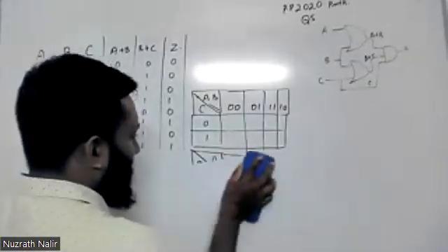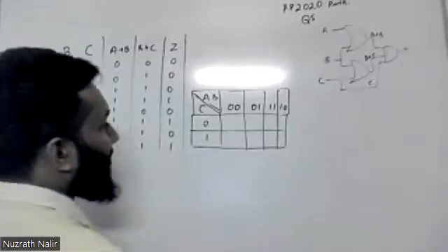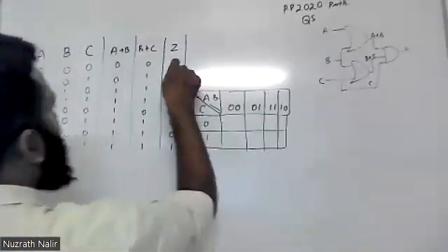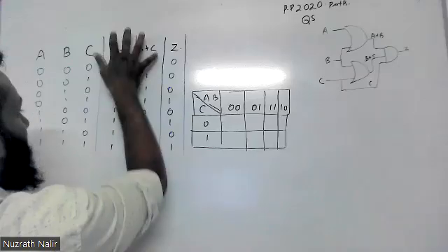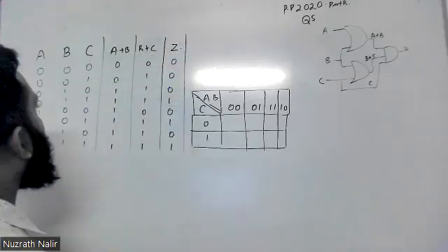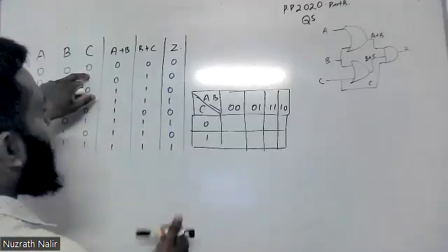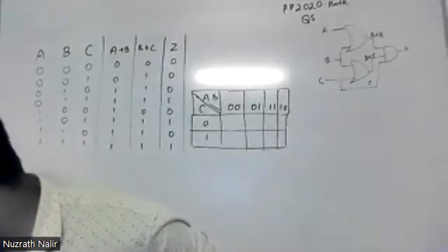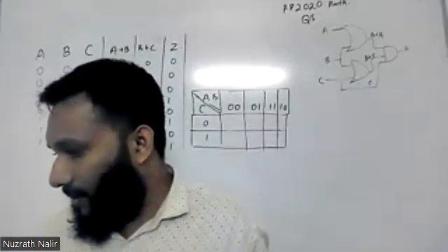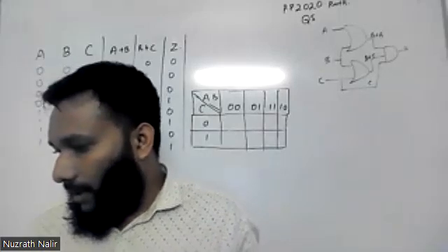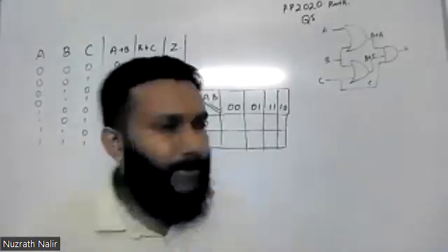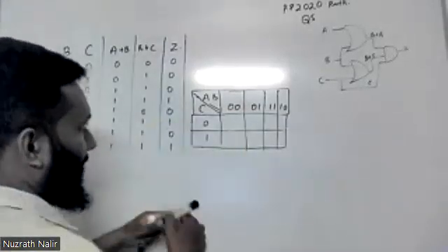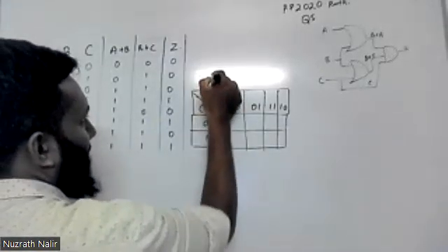So both are correct. I'll just use this vertical, horizontal format. So here this is your final output, no need to worry about this one. The final output is 0, 0, 0, altogether 0. They have mentioned using Karnaugh maps, derive a simplified sum of products expression for the output Z. In this scenario, you can mention only the ones because this is the SOP format.